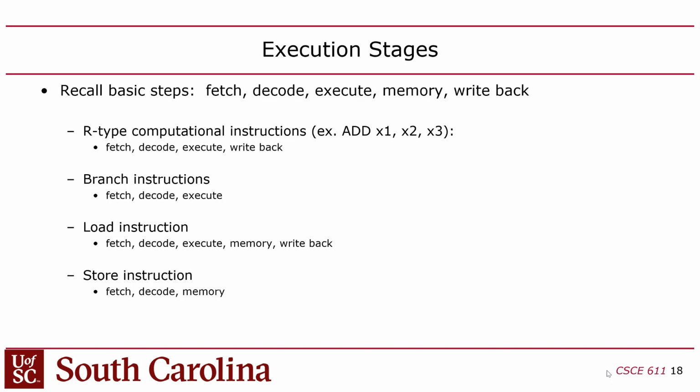Okay, so instruction fetch means one cycle is devoted just to fetching the instruction, which we have to do because we have a synchronous read on that instruction RAM. Decode is reading the registers out of the register file and decoding the control signals, doing a lookup in the control signal table. You guys with me?